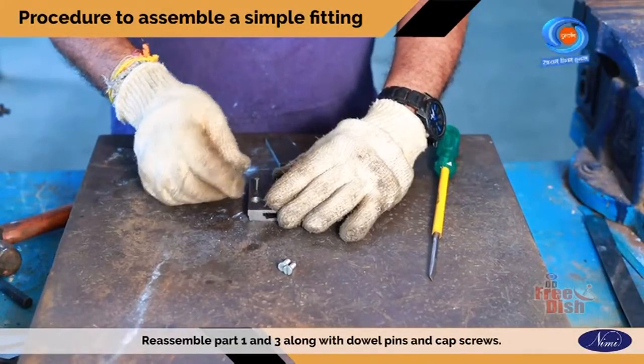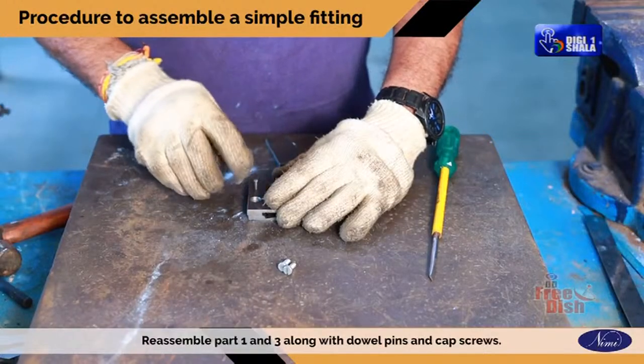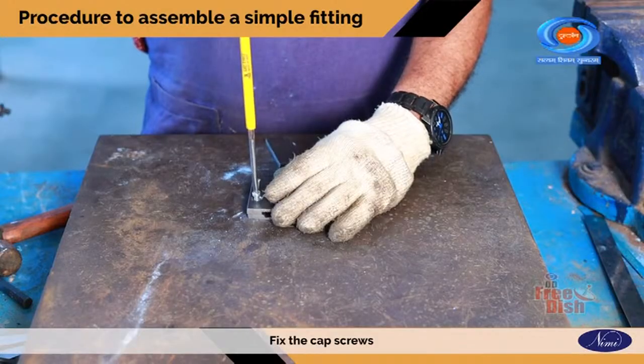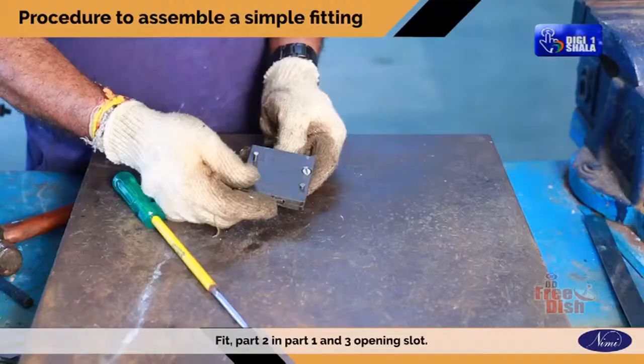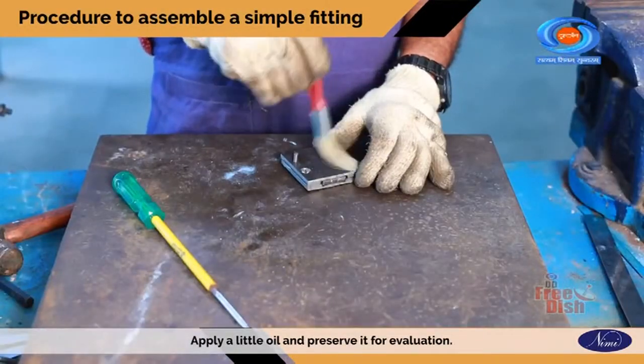Reassemble part 1 and 3 along with the dowel pins and cap screws. Fix the cap screws. Fit part 2 in the opening slot of part 1 and 3. Apply a little oil and preserve it for evaluation.